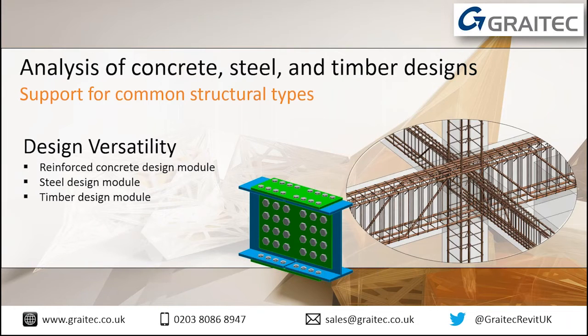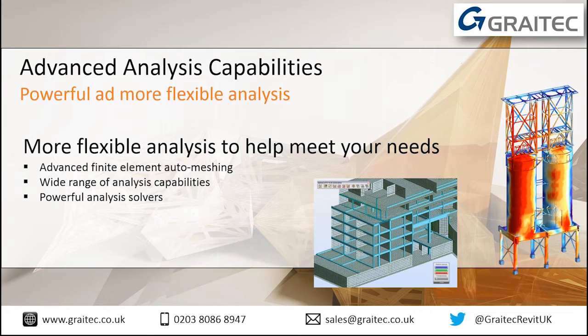So the sort of things you're going to be able to do within Robot itself is some analysis for concrete, steel and timber design. Okay, so it's making your design a bit more diverse, because you'll be able to design the reinforced concrete frame or the steel frame or the timber frame inside one actual environment. It does have further capabilities. You can take the actual design further and utilize the tools inside Revit itself. We have auto meshing there, so it will actually demonstrate and show you in color, and you can show other elements of the analysis within there. For example, if you're showing your bending moment diagrams, you can highlight all that information in there, and it can be displayed on screen.